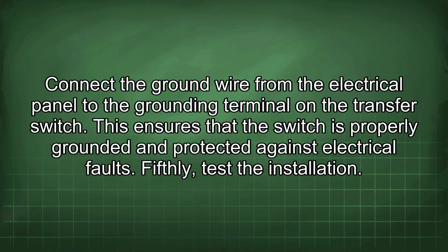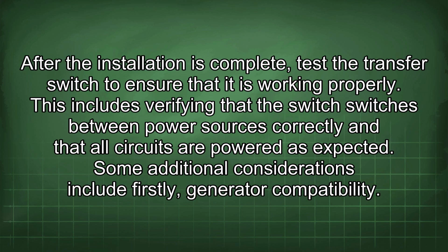Connect the ground wire from the electrical panel to the grounding terminal on the transfer switch. This ensures that the switch is properly grounded and protected against electrical faults. Fifthly, test the installation. After the installation is complete, test the transfer switch to ensure that it is working properly. This includes verifying that the switch switches between power sources correctly and that all circuits are powered as expected.